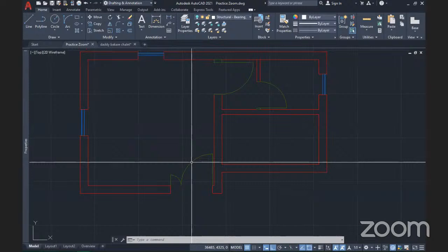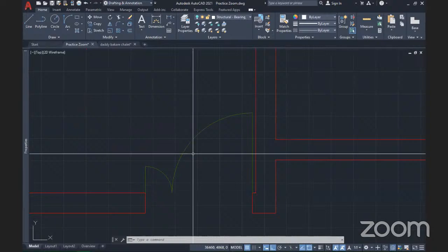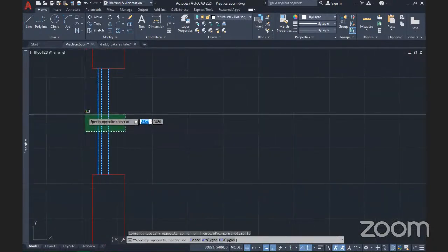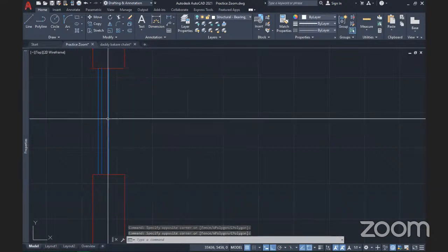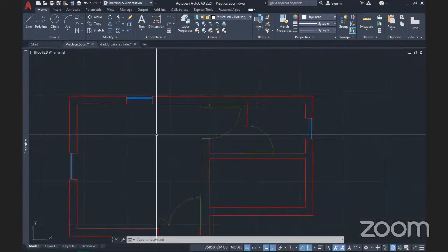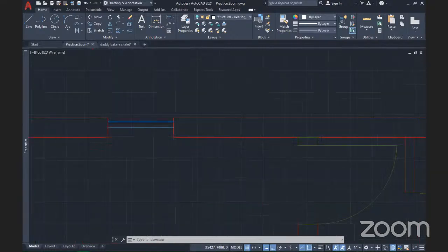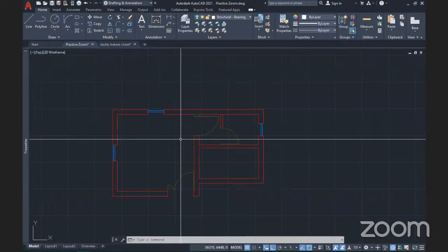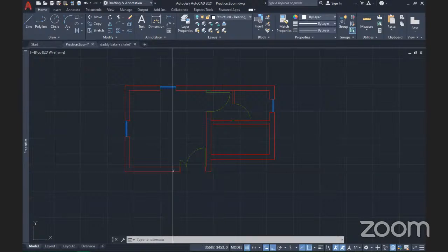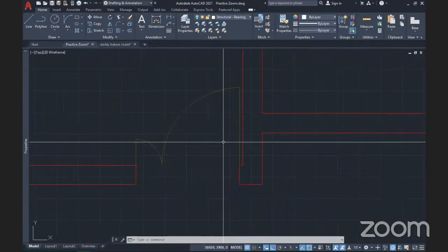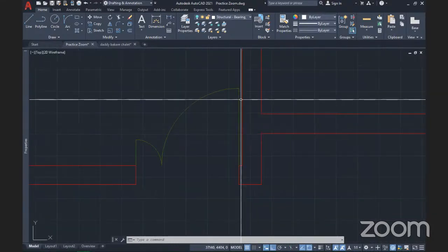If you notice, especially for the door illustration and the illustration I use for the windows here in this drawing, you see that all these lines are segregated. They are not together. And if I want to repeat these lines, that means I'll have to redraw them or copy these lines one after the other. And that can be very, very tasking. There is something called blocks in AutoCAD, and with that, you can organize your drawings in such a way that, okay, if you want to edit any of these illustrations or any of these objects, you can just go to the blocks and edit them.